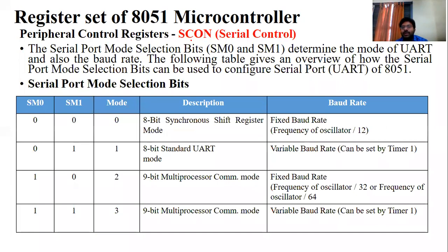For serial mode in the 8086 microprocessor, you can use the USART as one of the interfacing devices. USART is universal synchronous asynchronous receiver and transmitter. Here it can be represented as UART. So you don't get confused in your examination, you write USART.